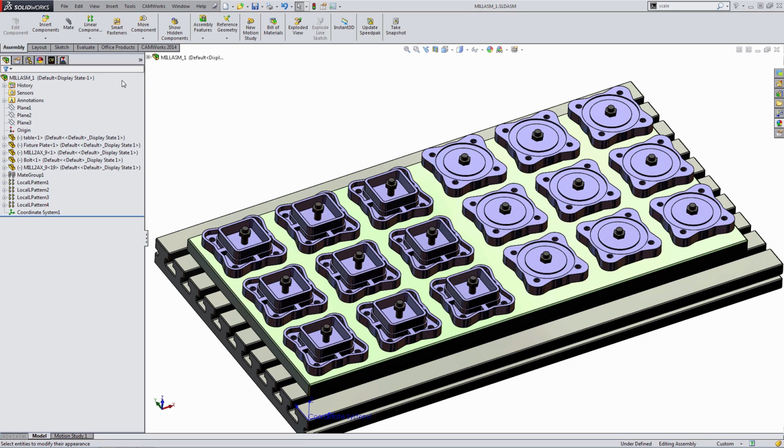It's a SolidWorks function in the SolidWorks assembly tab. If you can't remember where it's listed, it's going to be listed under reference geometry. But if you can't remember, there's always the nice search box up top. You can start to type coordinate system and it brings it up for you. And then if you want a nice reminder of where that is, you can hit the little eyeglass icon and it'll point it out for you.